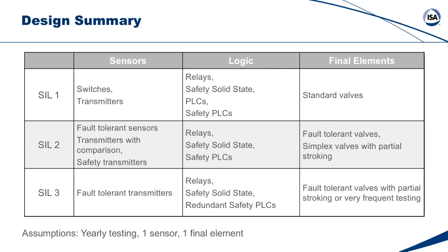But if you have a 5-year test interval, you probably don't even meet SIL 1. So if you think, well, we have a 5-year turnaround period, then you need to build a new cookbook based on actually doing PFD, probability of failure on demand calculations, to see what is it going to take for your design based on your hardware and your practices. But systems need to be tested much more often than every 5 years, I'll simply put it that way. SIL 2 tends to get expensive. Now, I have not covered the fault tolerance tables in the standard and other more details like safe failure fraction.